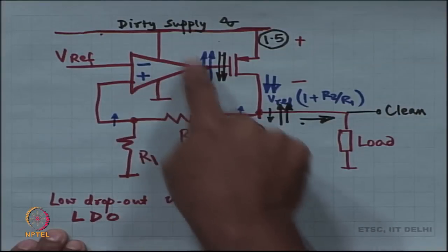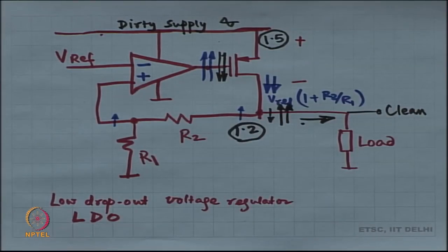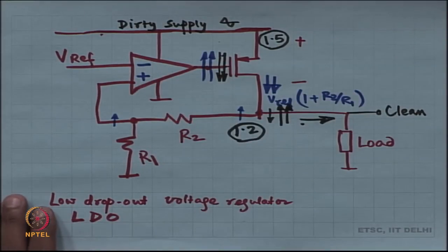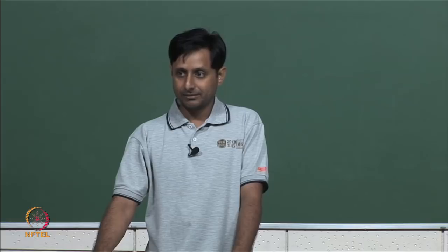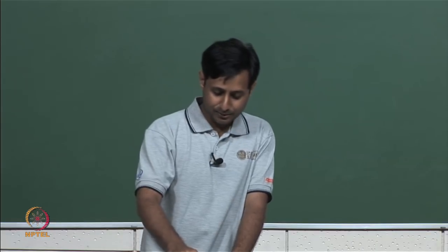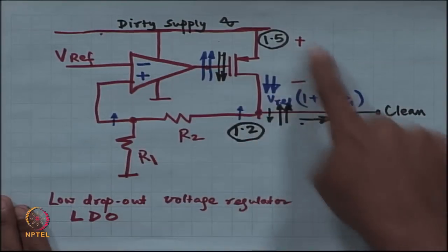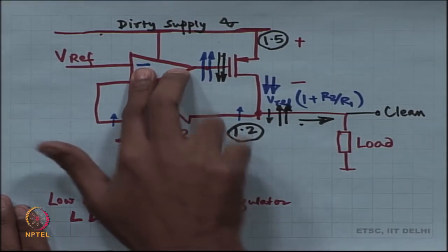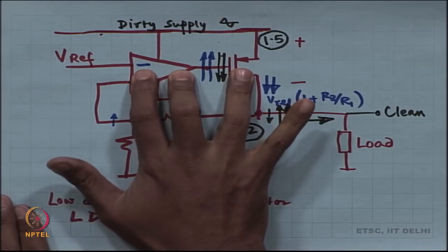I mean, if you just compensate this 2-pole or original amplifier, it is not going to be good enough. You have to compensate this entire 3-pole system. Okay. So, this is going to be much harder, much harder. When you do your compensation of this particular structure, it is going to be much harder because there are 2 poles in this plus one more pole, 3 poles, right.